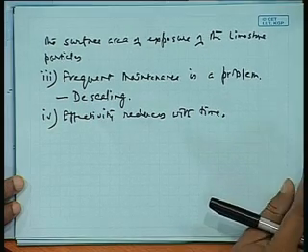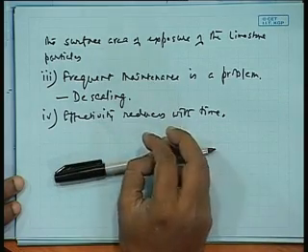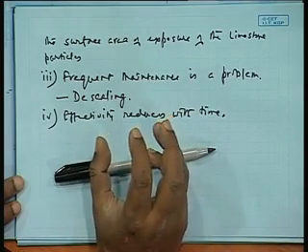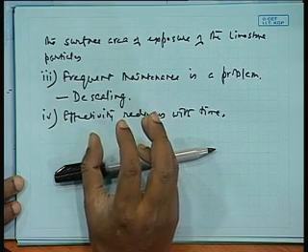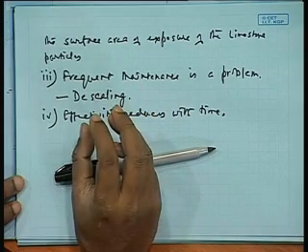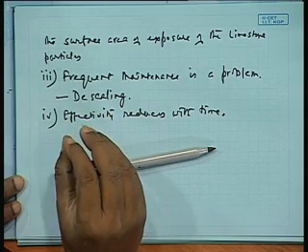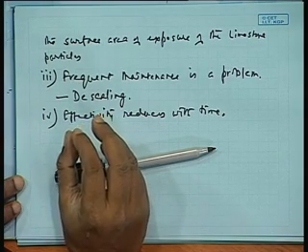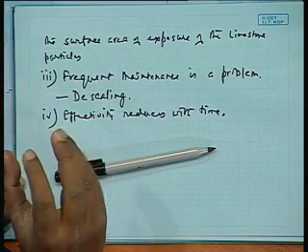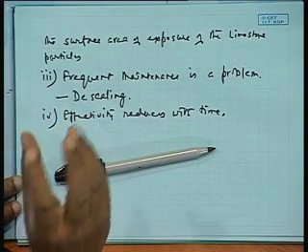Let me explain this again: the amphoteric property suggests that all metal hydroxides and metal sulfides have minimum solubility at a particular pH. So at that point their solubility becomes minimum. For our plant design specification, we like to keep the water at those particular minimum pH values, so that the solubility of the metal hydroxides in water becomes minimum at STP that we consider.